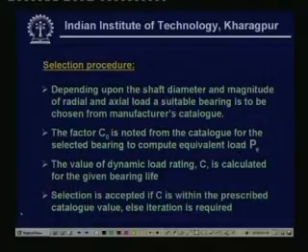Now, you know the amount of radial load and axial load acting on the bearing. So, knowing the shaft diameter, you can find from the manufacturer's catalog what the diameter of the bearing should be. Here I would like to suggest one thing: you know the radial component and the axial component, so automatically you can find out what type of bearing you are going to use, either a ball bearing or a roller bearing or something like that. But one thing is to be mentioned: the expression for equivalent load described here is normally for bearings having more of the radial loads. Little changes come in equivalent load calculations for the taper bearing, but the ideas are more or less the same.